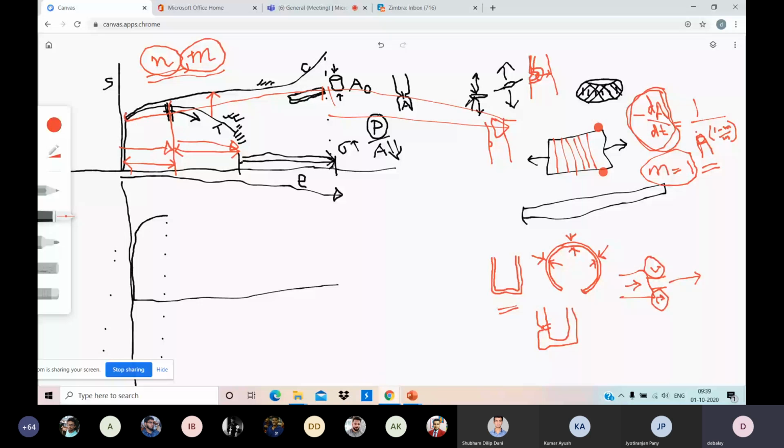It generally merges with tension for the same material, but post yield it may be a little high compared to the tension curve. The compression curve remains on a higher side. Why? Who can tell? Very practical sense is needed to answer this, and the gap will continuously grow.